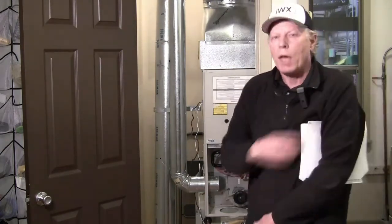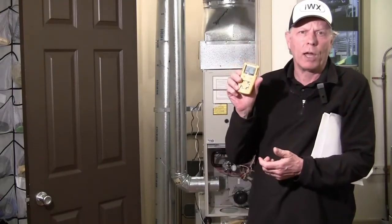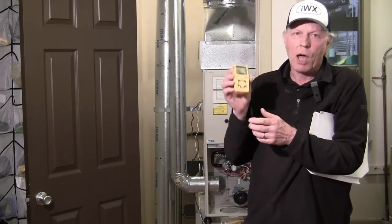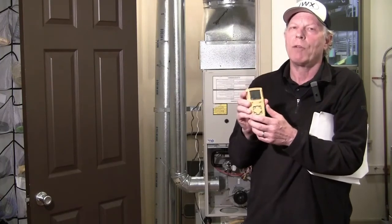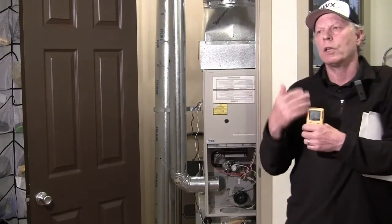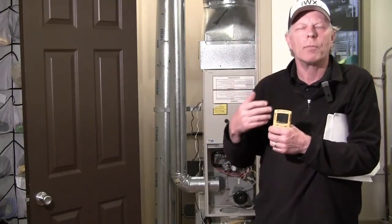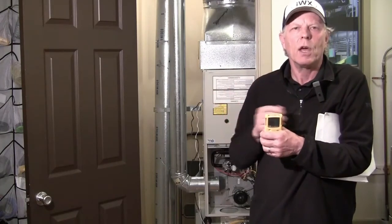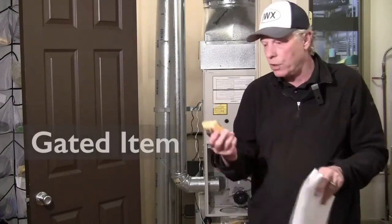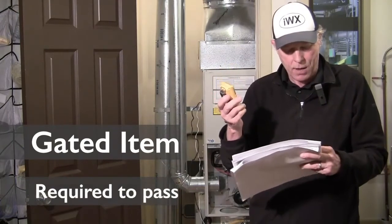So you want to make a habit of carrying this 4-gas monitor here that's going to measure ambient CO for us, and it'll constantly monitor ambient CO, but you need to look at it from time to time. The combustion sheets we use in the state of Washington actually ask you to check your CO 3 or 4 times during the test. This one is automatically having you check, on line 7 when you come across it, you'll pick this up and you'll say, I have 0 ambient CO, all right?